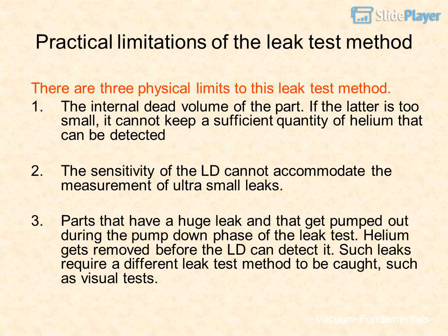Practical limitations of the leak test method. There are 3 physical limits to this leak test method. 1. The internal dead volume of the part. If the latter is too small, it cannot keep a sufficient quantity of helium that can be detected. 2. The sensitivity of the LD cannot accommodate the measurement of ultra-small leaks.